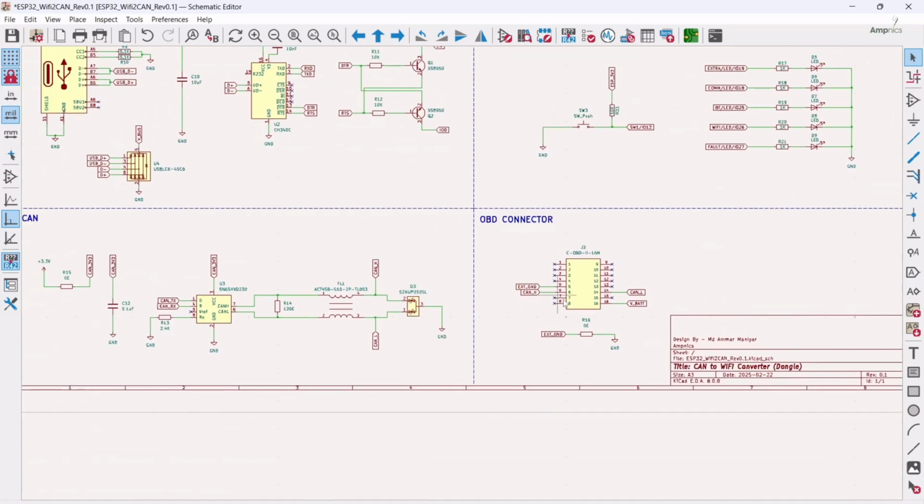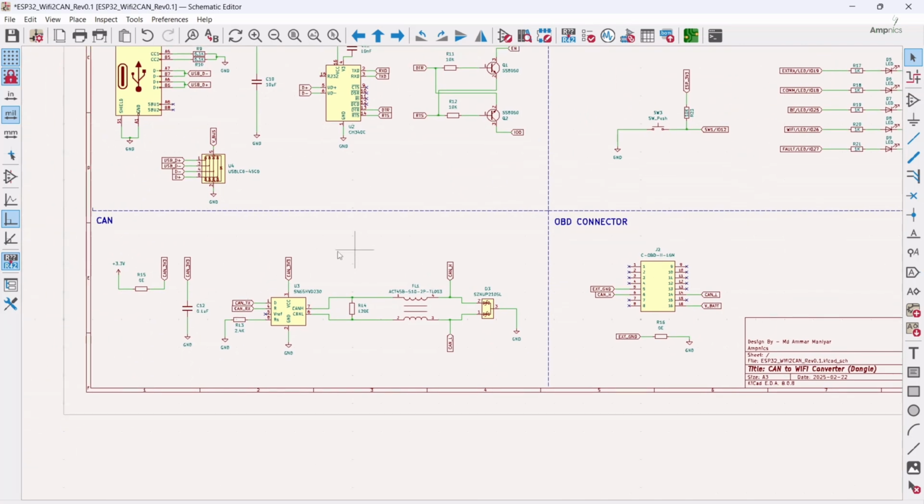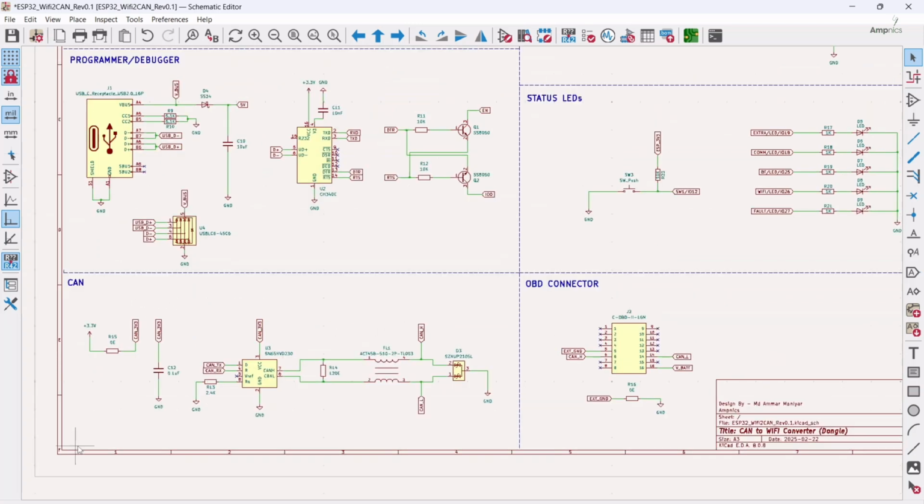With the help of this, you can measure the current, if you are concerned about how much current each and every block is consuming. With the help of a 0 ohm resistor, you can measure it, because it is connected in series. You can put the multimeter over here and check the current. This 0 ohm resistor offers so many benefits in the circuit, so for that reason, I use it a lot.